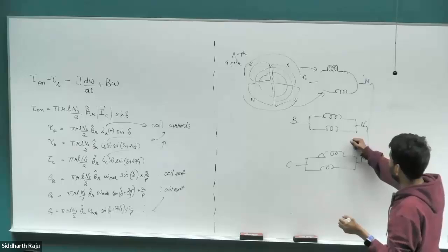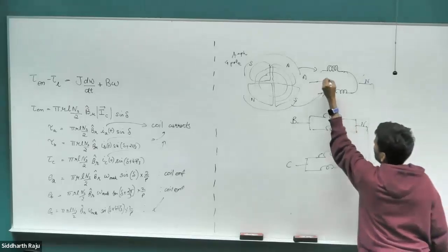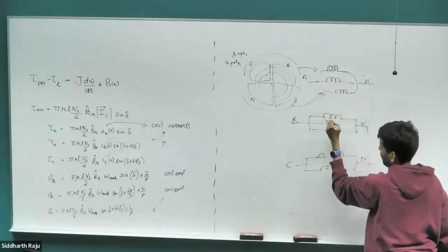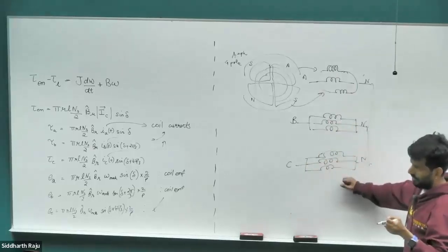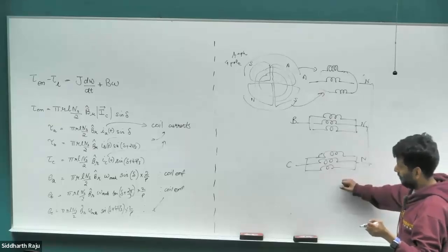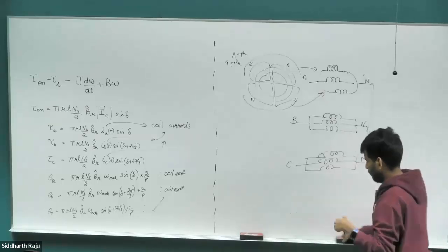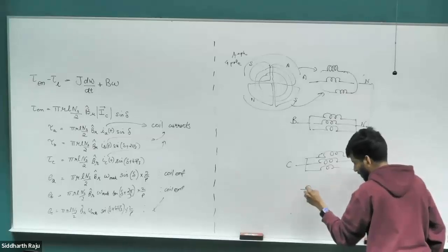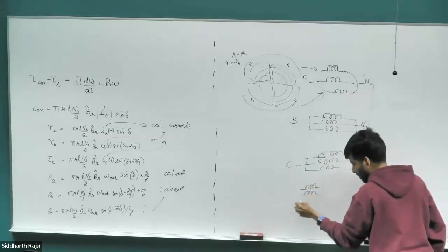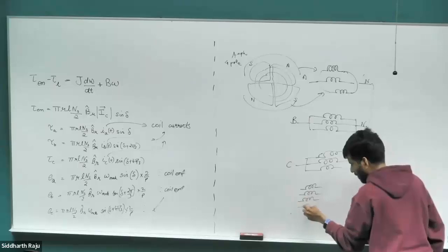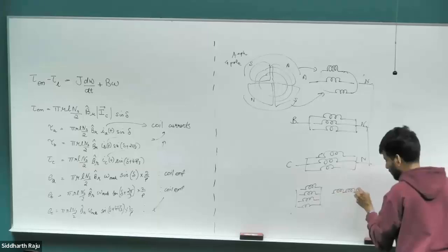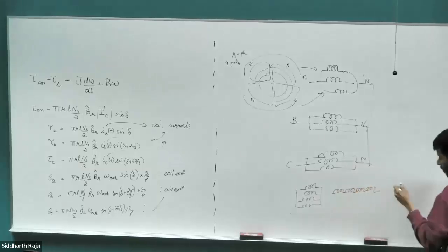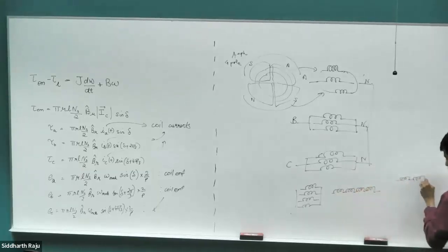When you have the 6-pole case, you have the option of putting these coils again in parallel, or you have the option of connecting these coils in series. Now, when you get to the 8-pole case, you can do something a little bit more interesting. In case of an 8-pole case, you have multiple configurations. You can have the 4 pole pairs in parallel. You can have the 4 pole pairs in series, or you can have 2 of them in series and 2 of them in parallel.